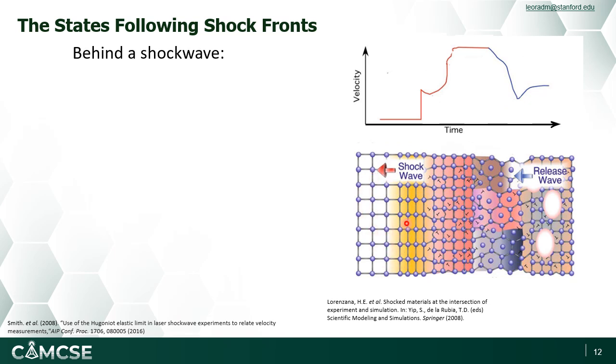Our initial shock is what's called a uniaxial shock along only one direction, as we see in yellow here, that is effectively a reversible wave that at some point, of course, becomes irreversible. We can say that effectively this wave is traveling so fast that it outruns the plasticity and failure of the material that would be required to see anything that is off axis from just uniaxial compression.